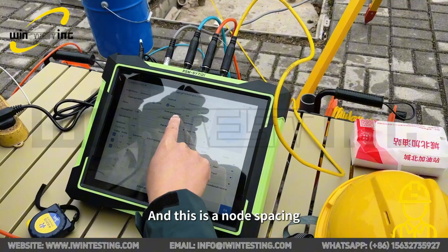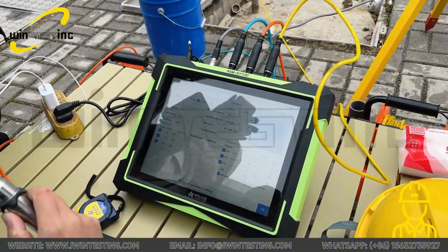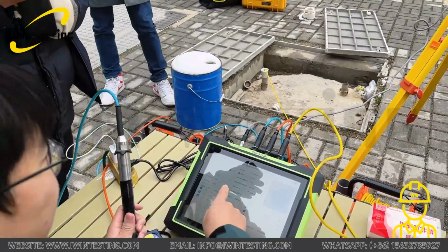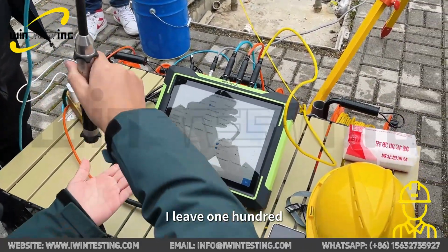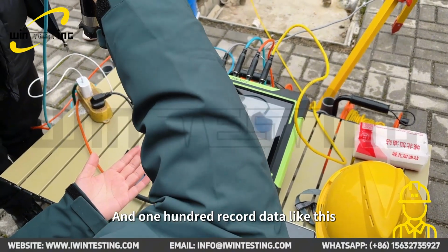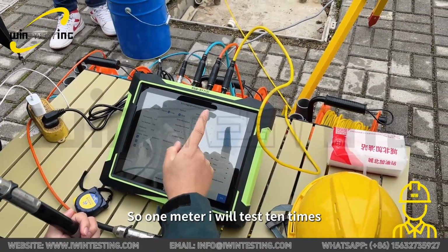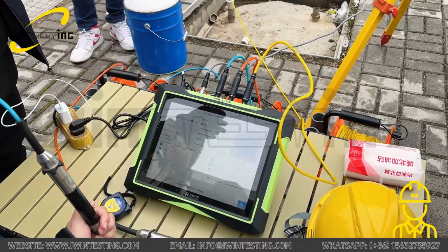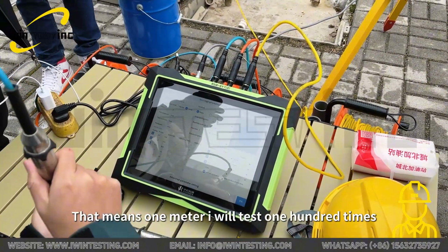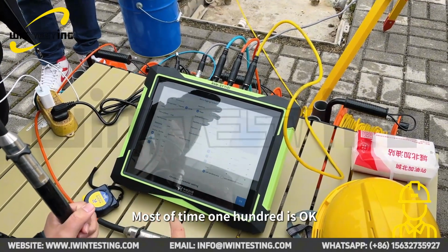And this is the node spacing. Node spacing is how much we lift the probe. If I set 100, I lift 100 mm and record data, like this. So if I set 100, for 1 meter I will test 10 times. If I set 10, that means for 1 meter I will test 100 times. Most of the time, 100 is okay.